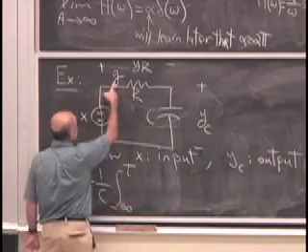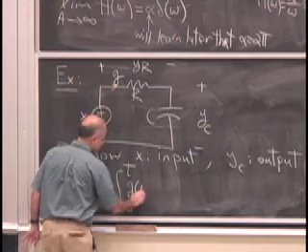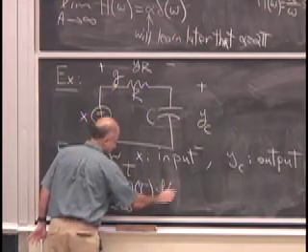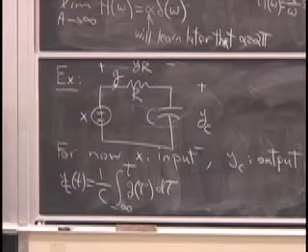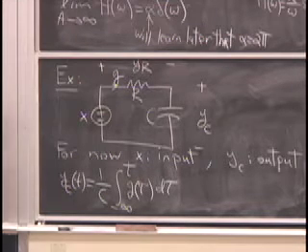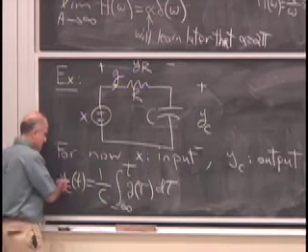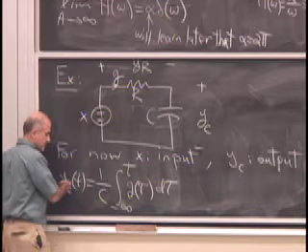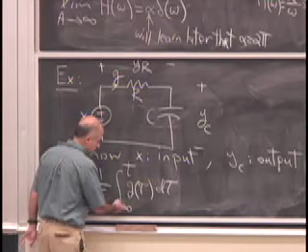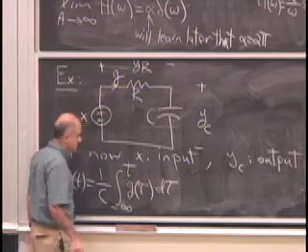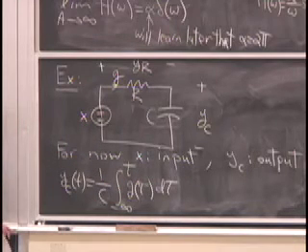In this case, that current I've represented with G. Notice I'm scrupulously avoiding I. It's one of the clashes we have with circuits courses, because we use I for the square root of negative 1. So the voltage across the capacitor is 1 over the capacitance times the integral from minus infinity to t of the current.